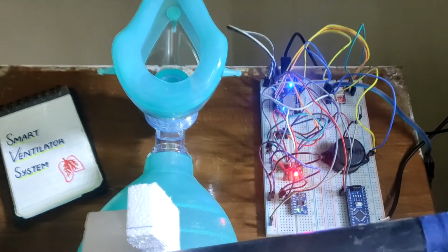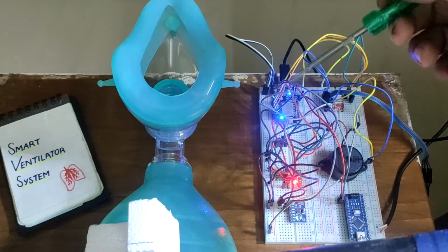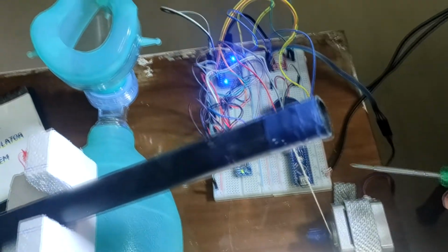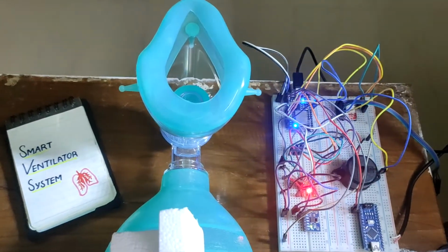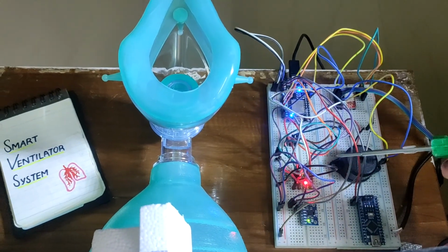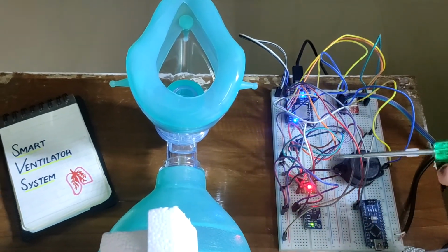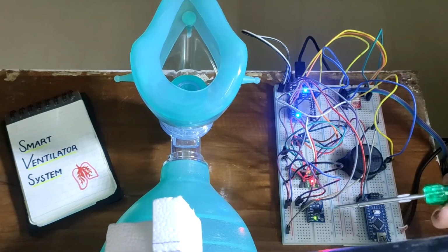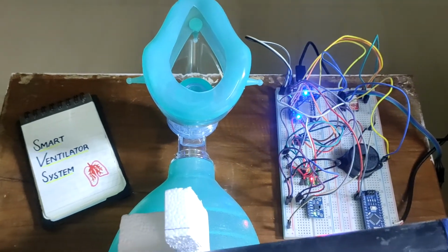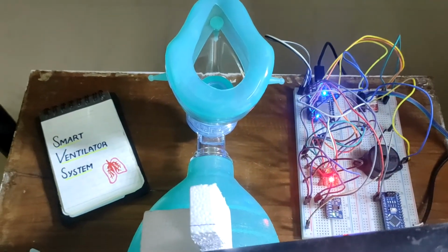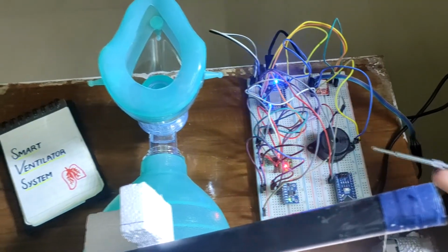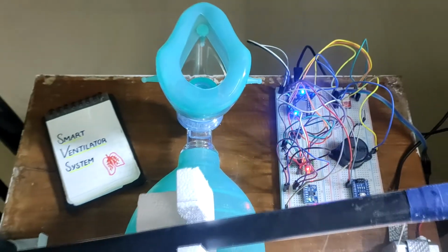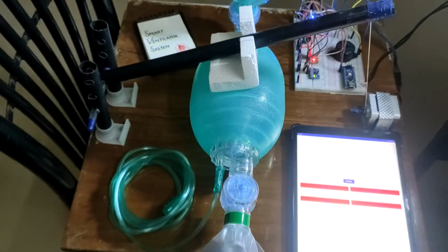The microcontroller used is the Node MCU with ESP8266 at heart. We're also using an Arduino Nano to offboard some of the computation from the node, which will communicate over serial. We're also using the MAX 30100 pulse oximetry sensor for SpO2 and heart rate, and a 3-axis accelerometer and gyroscope to track the patient's diaphragmatic movement to analyze his or her respiratory pattern. An additional buzzer is added to the circuit to give a feedback for every detected heartbeat. Well, that pretty much sums up the hardware components.